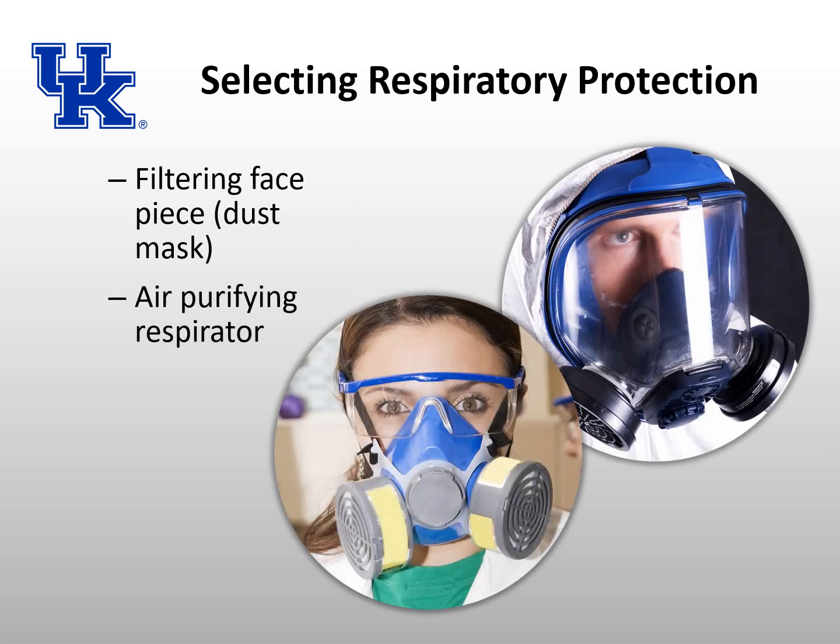Air purifying respirators, either full face or half face, are the most common type of respiratory protection. These respirators use cartridges or filters to purify the air being breathed in and provide protection against vapors and fumes. Air purifying respirators must be worn by workers when monitoring shows the PELs have been exceeded. At levels below the PEL, you may choose to wear a respirator.